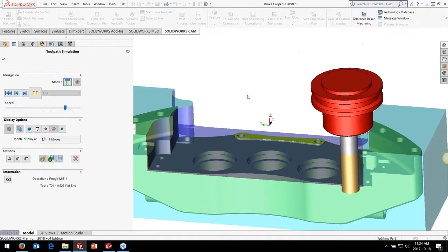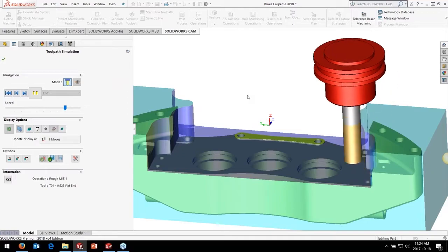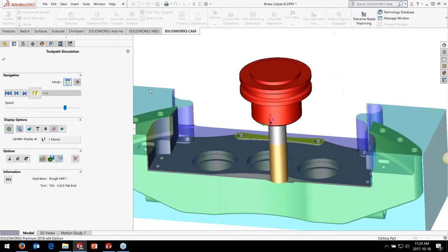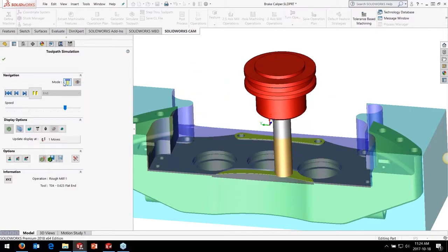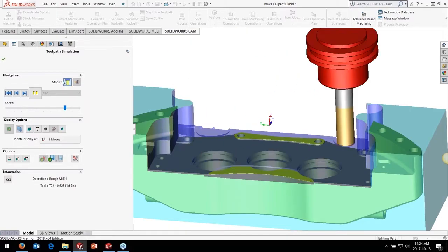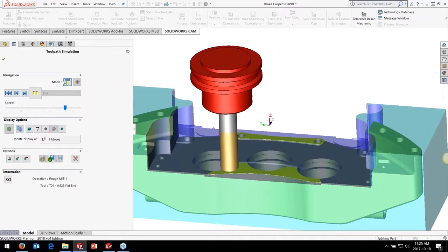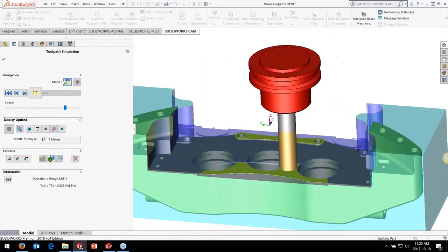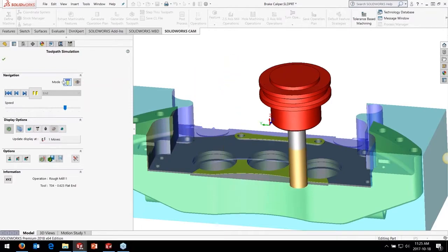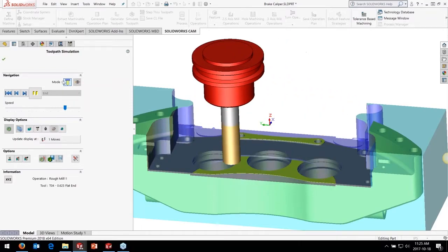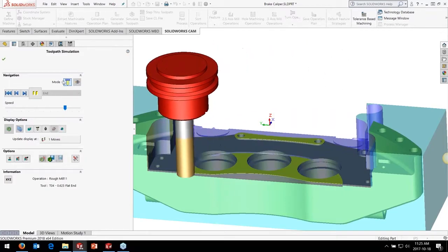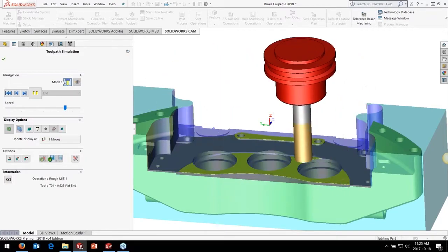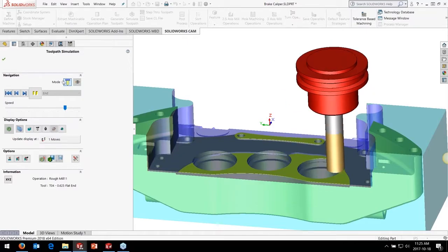So it puts a huge amount of wear on the tool, going from essentially 0 to building up the speed. It slows the spindle down so you're not getting optimal cutting. It's basically why you use a lead-in feed rate, so you can slowly come into the part and then start ramping up the geometry. But what this does is it automatically calculates it to adjust that feed rate as it's coming into the material, and then as it's coming out of the material, it will speed it up to get back to the other side again.